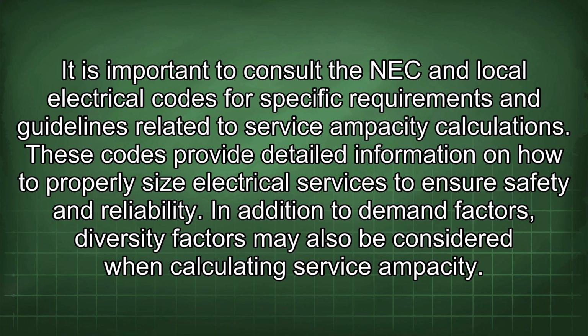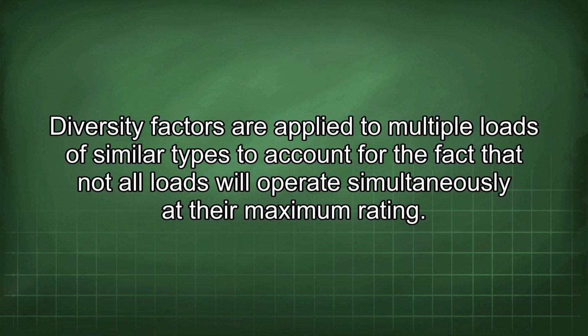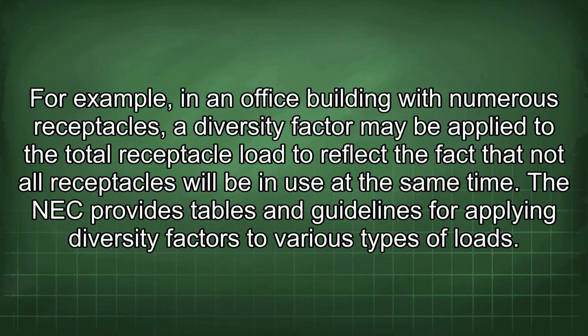In addition to demand factors, diversity factors may also be considered when calculating service ampacity. Diversity factors are applied to multiple loads of similar types to account for the fact that not all loads will operate simultaneously at their maximum rating. For example, in an office building with numerous receptacles, a diversity factor may be applied to the total receptacle load to reflect the fact that not all receptacles will be in use at the same time.